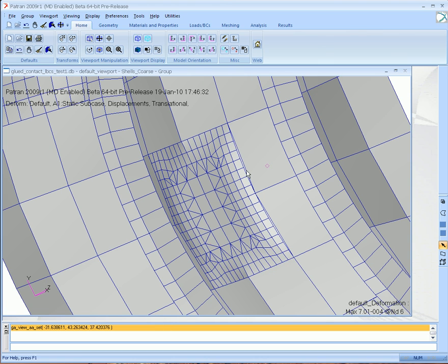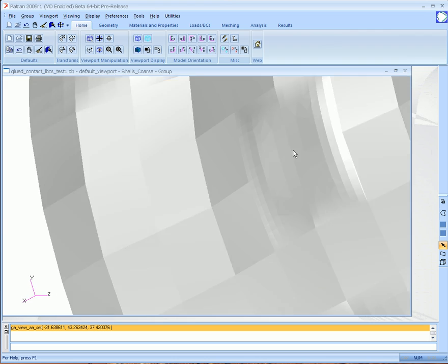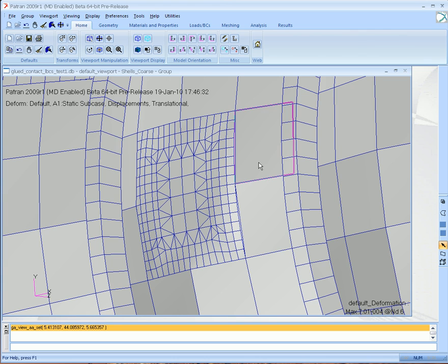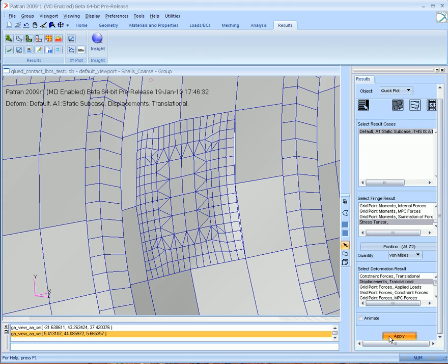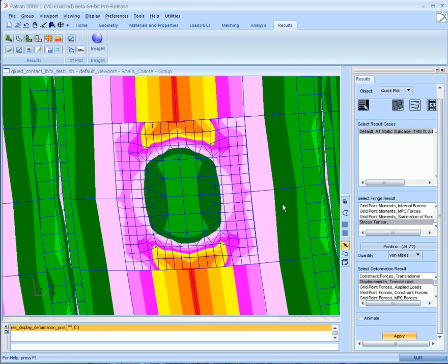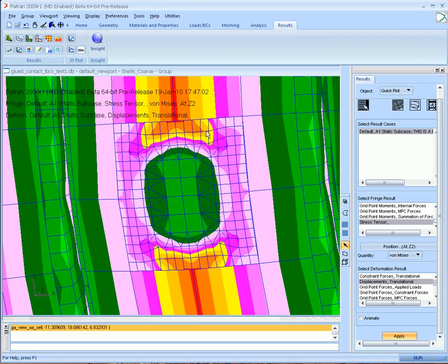So we see an opening here, but that's actually just a visual scaling of the opening. The thing does not really open. When you actually have the opening, it becomes quite clear, and also you have a discontinuity in the stress field, which is not the case here. If we look at the actual stress field at this boundary, we have continuity in the stress field pretty much.